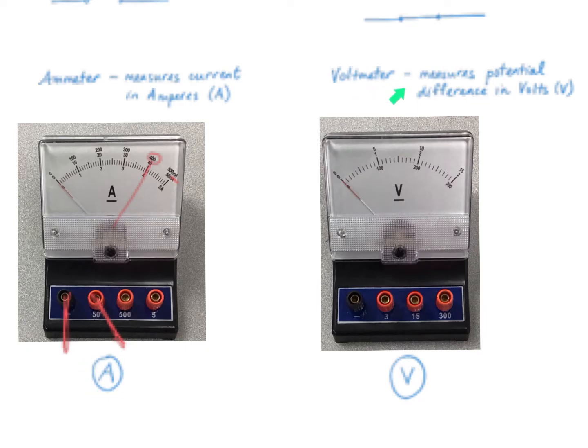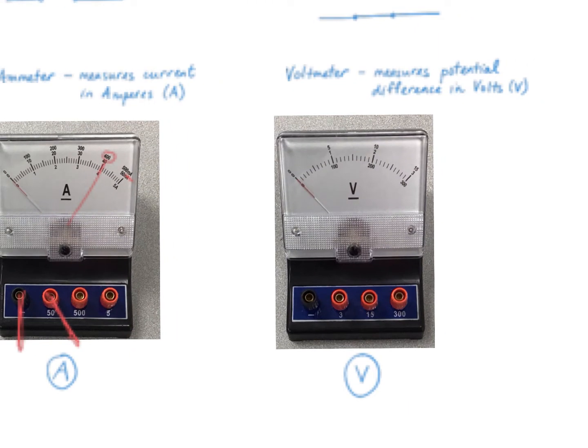A voltmeter, on the other hand, measures potential difference, so the voltage drop across a load or an energy source. I'll show you later on how we connect that, but here's the symbol for it, V in a circle. So this is a voltmeter, and again, we'll have a wire going here, and you have choices of 15 or 3 here. We're really looking at the 3, okay? The batteries that we're using, we're working really around the 3 volts. That's a better range. So we would be reading the middle scale of numbers here.